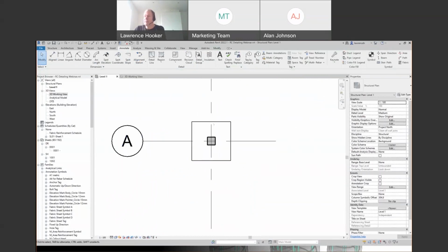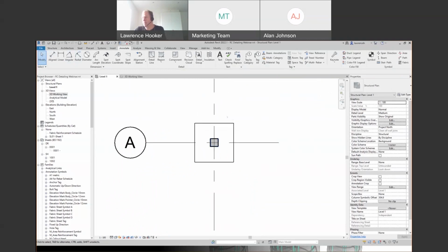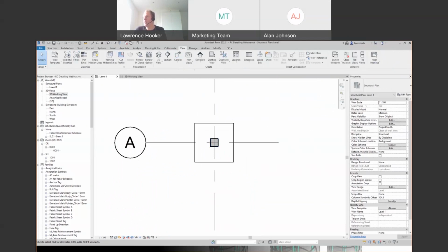Okay, so like I've said, the only technology we're using here is out of the box Revit and a template. So let's begin by placing in some reinforcement into our foundation. So I'm going to start by cutting a section through this. We can just go to the View ribbon over here. We can then go ahead and select the Section tool.